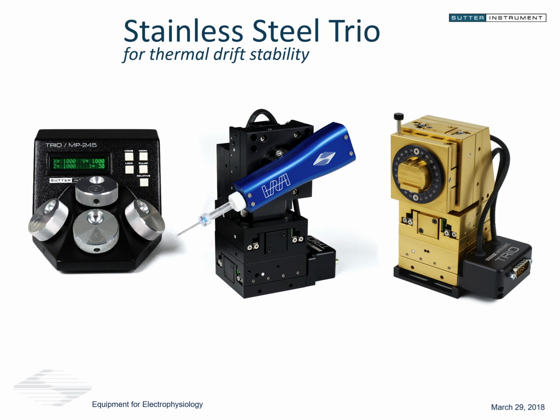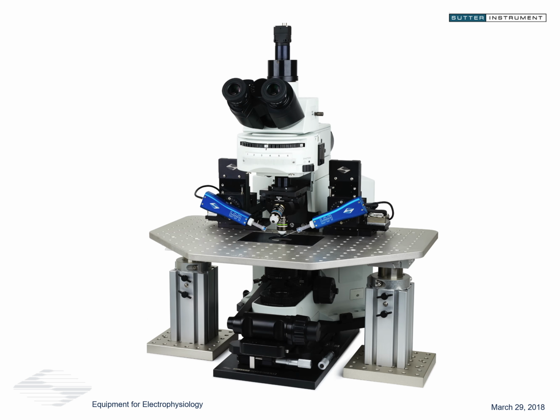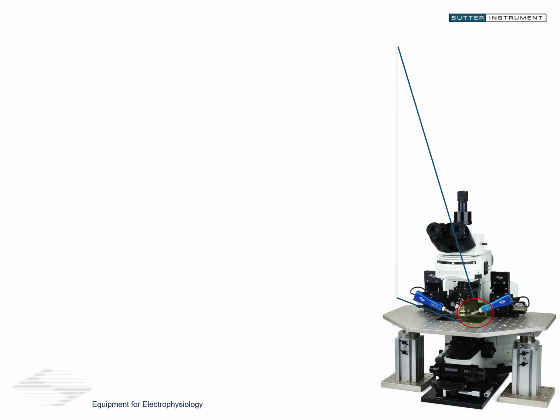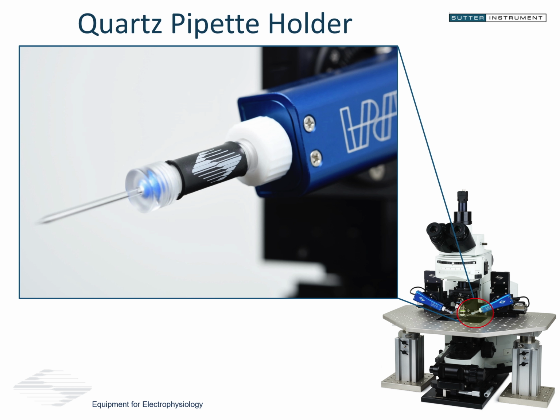Now, if we're talking about the manipulator and thermal expansion, as we've investigated the properties of an electrophysiology setup to find some of the problematic areas for these types of instabilities, we noticed that the head stage, and in particular the pipette holder itself, is a source of some of these instabilities. So what we've done is we've developed a quartz pipette holder. This is a relatively small component, but it can make a really big difference. So how much of a difference can it make?